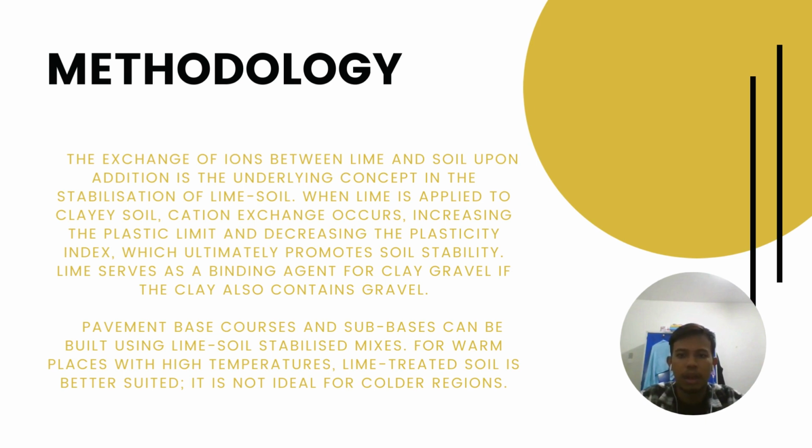The exchange of ions between lime and soil upon addition is the underlying concept in the stabilization of lime soil. When lime is applied to clay soil, cation exchange occurs, increasing the plastic limit and decreasing the plasticity index, which ultimately promotes soil stability. Lime serves as a binding agent for clay gravel if the clay also contains gravel. Pavement base courses and sub-bases can be built using lime stabilized mixes for warm places with high temperatures. Lime-treated soil is better suited there. It is not ideal for colder regions.